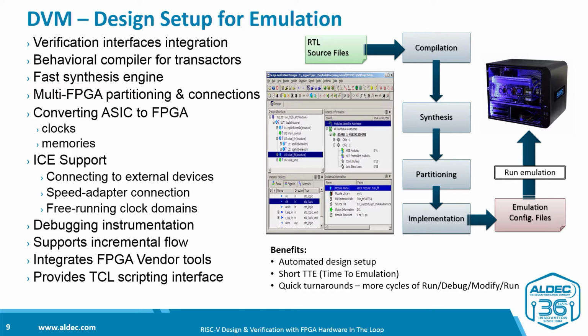DVM, which is Design Verification Manager software tool, it's for design setup automation. It will guide you starting at RTL source compilation through synthesis, partitioning, and FPGA bit file implementation. DVM provides two distinctive design flows, one for emulation and the other for prototyping. In emulation mode, that also includes simulation acceleration, DVM integrates verification interface with your design and provides behavioral compiler to convert transactors, monitors, and similar test bench components to FPGA.